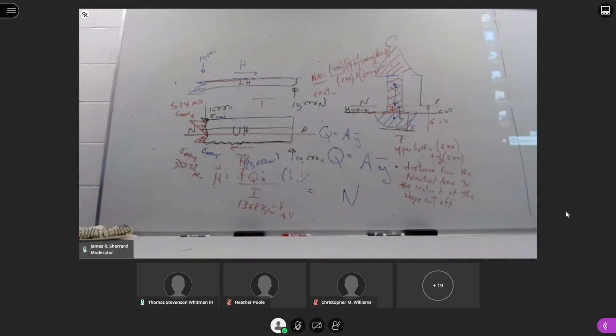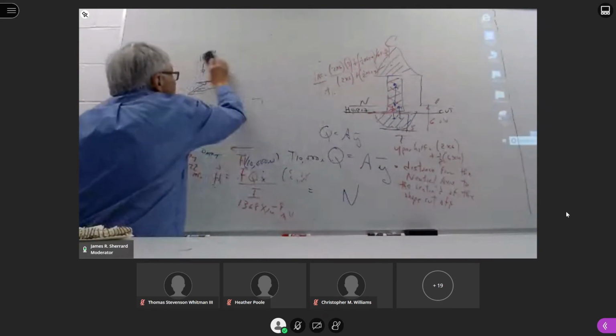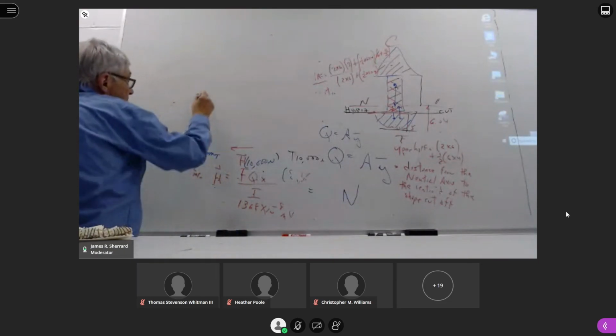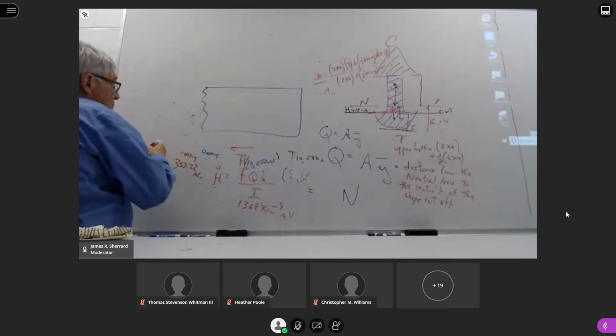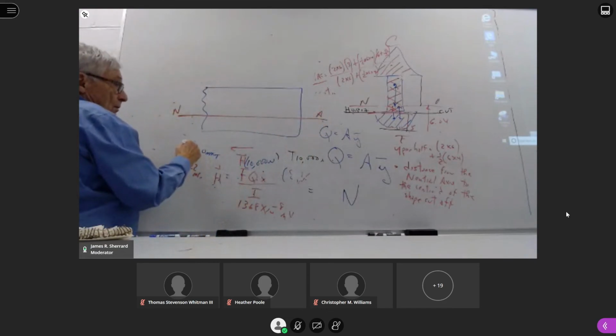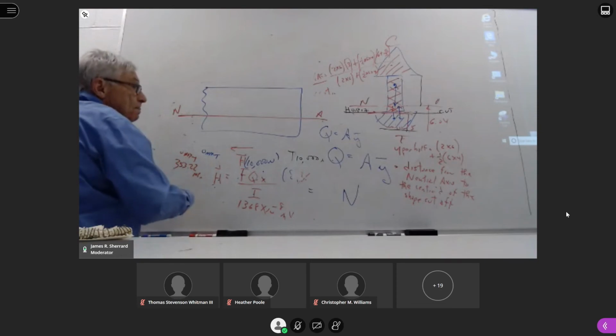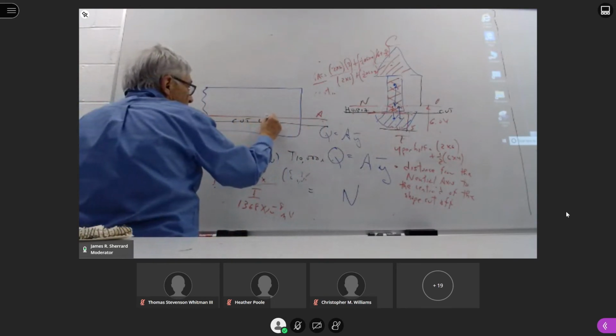Can we talk about the forces on the left-hand side where we changed the 80,000 Newton meters into the compression and tension formula? Yes. Yep. So the neutral axis is going to be above that cut line. Yes. So let me erase this. Let me go back and resketch this whole thing. This is 5 centimeters up where I cut it. This is my cut line.